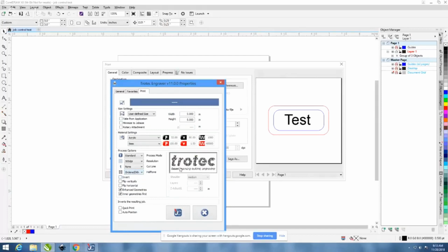Yeah, so when you take a color photograph to send it to the laser, obviously the laser can't engrave in color. So it does a process called dithering. It's taking a series of a dot pattern to approximate the colors in your drawing. And these are the different methods that it uses to do it. The ordered dithering is basically a fixed pattern throughout. Some people really like it. They think it looks great. I find that pattern to be kind of distracting, so I personally don't like it. That's why I prefer Stucki like Anthony does. But some people really prefer it. So like Anthony said, beauty is really in the eye of the beholder.